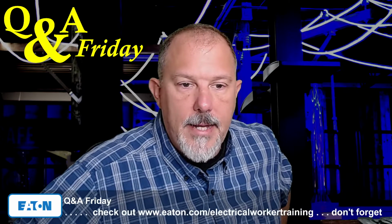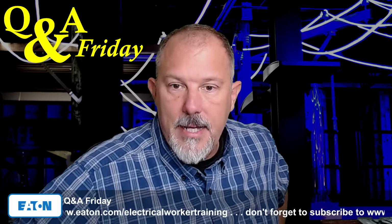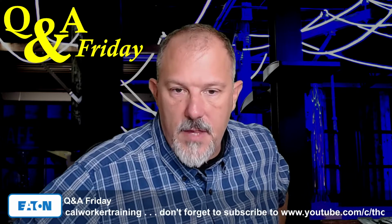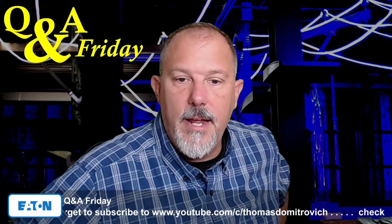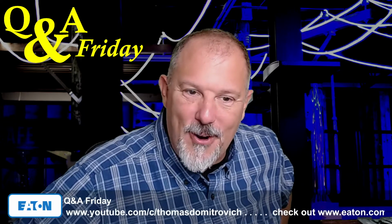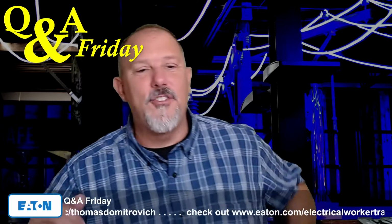Okay, can cable limiters ever be used to accommodate lower fault current ratings on equipment? Never seen it done this way, but wondered if it was allowed. I would think there would be a concern with parallel runs of making sure they all operate, both for purposes of clearing the fault and also to make sure you don't have just one open, creating overload on the other conductors if the circuit survives the fault and is re-energized.